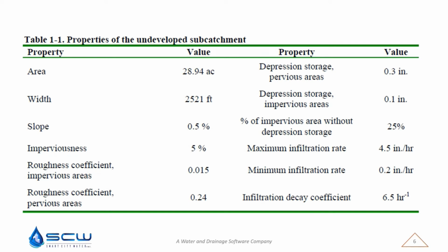One of the most common ways of calculating the width of catchments in any SWMM engine software or any modeling is to calculate the longest overland flow length, and divide the area by the length of that longest overland flow, and we come up with the width of our subcatchments or catchments.